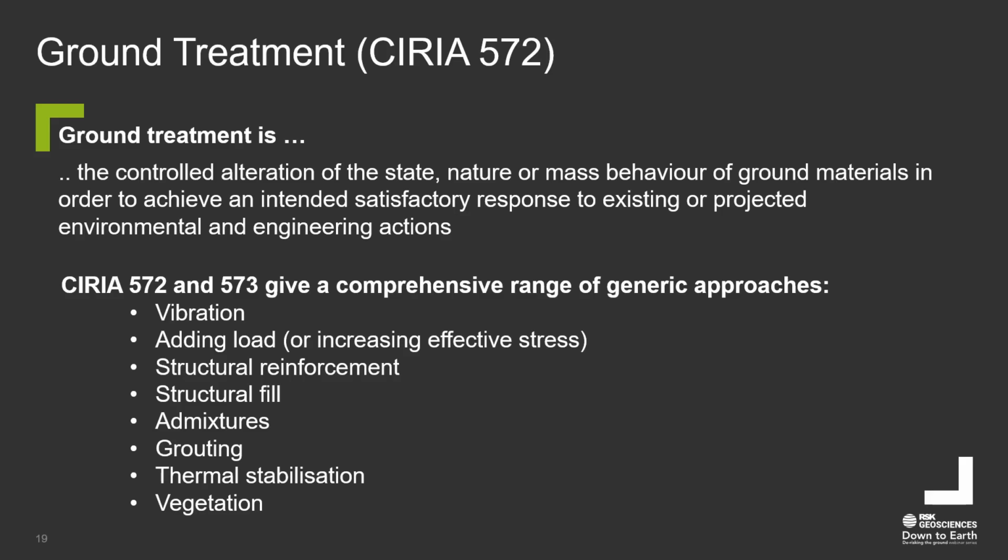Now, what we're talking about here is the soil type. If we've got a primarily granular material like sands and gravels, with a cohesive fraction, so with clays and silts in them, but primarily granular, then applying a physical energy, a vibration, a compaction activity will densify the soil, reduce its void space, and make it less prone to settlement under final building structural loads.